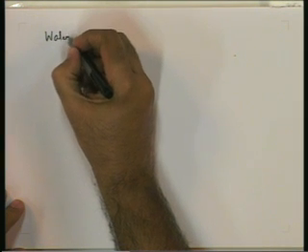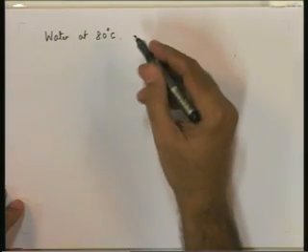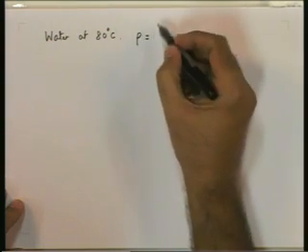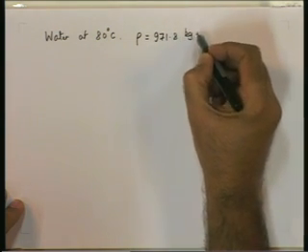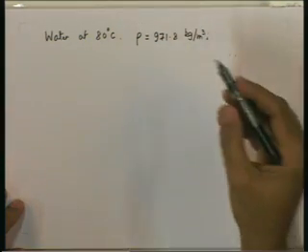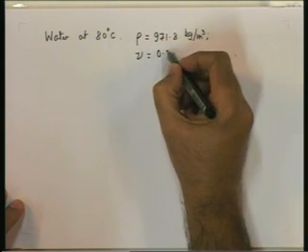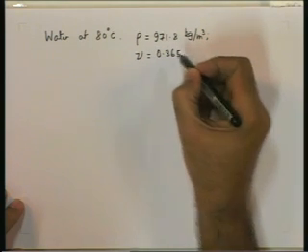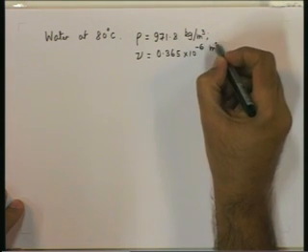And this is what will happen. We have now water at 80 degrees C. The density reduces slightly, 971.8 kg per meter cube, but the kinematic viscosity reduces reasonably significantly. Almost by a factor of 3.